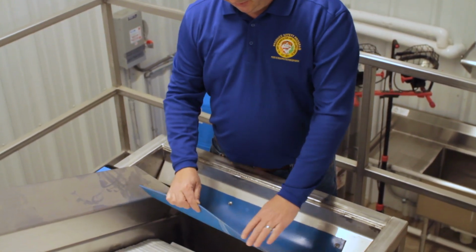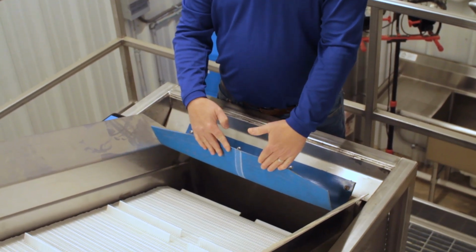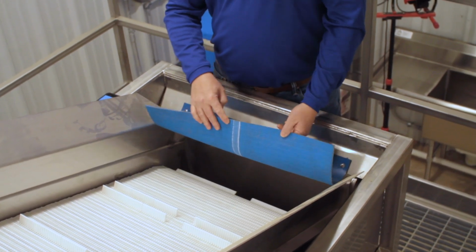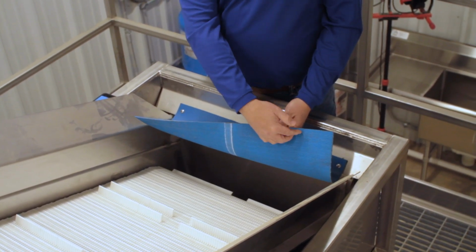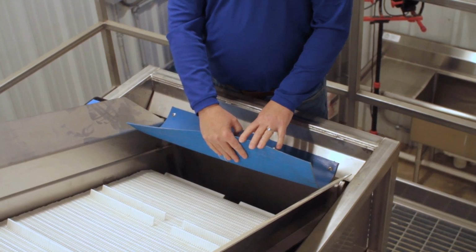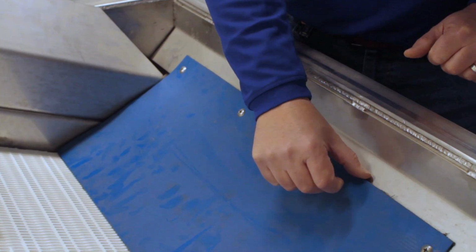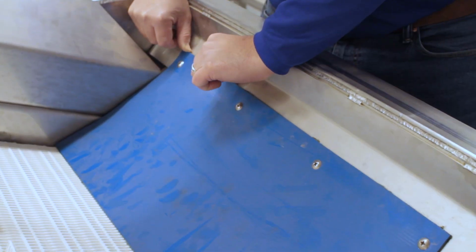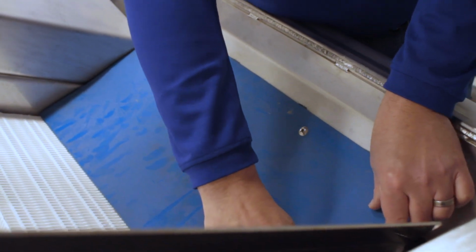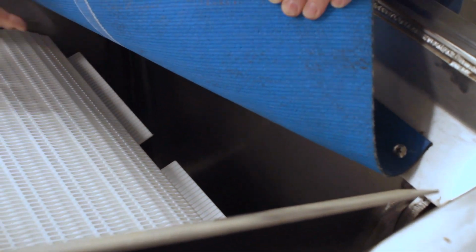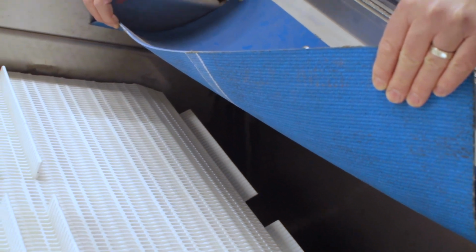As you're assessing your pack line equipment for cleaning and sanitation purposes, you'll see a lot of common materials used like this polyfibrous belt here. And with these polyfibrous belts, they will actually wick up moisture up into the back of the belt as some of these fibrous materials become more exposed. As you can see, you'd have to unbolt each one of these screws to remove this. So having quick release and having access to be able to remove these nuts and bolts is important for adequate cleaning purposes.